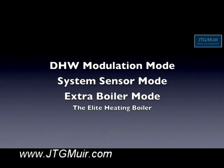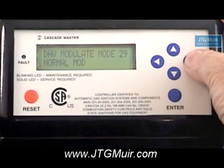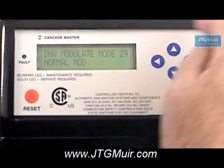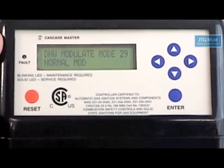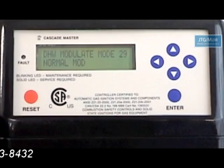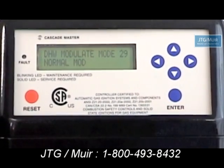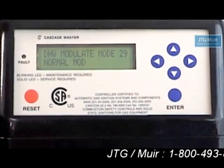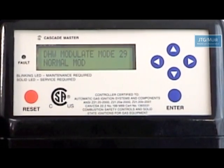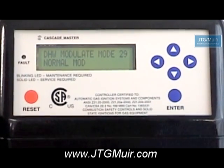Next thing, DHW modulation. As we mentioned earlier, when this boiler goes onto a heating call, the boiler modulates gradually up until it hits set point and then modulates back down. When you have a DHW call, domestic hot water, the boiler tries to heat the domestic hot water as fast as possible. For that reason, it starts modulating to high fire immediately.